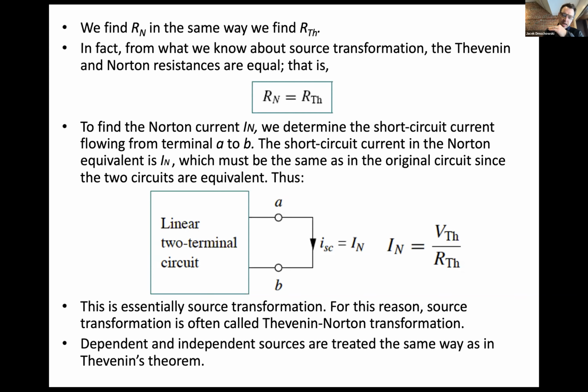And so, as in Thevenin analysis, if you have dependent sources in your original circuit, when you're solving for IN, you will keep those in. You will not disconnect the dependent sources. Remember, a dependent source responds to other branches of the circuit, so you cannot disconnect it.